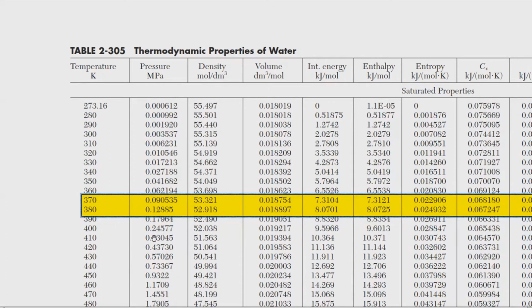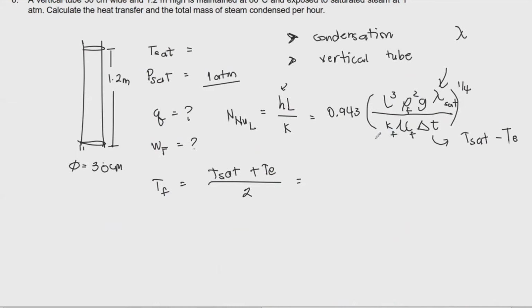That should be expected, but it's not really that exact 100 degrees Celsius. So with that, I still need to interpolate in between. Upon interpolation, by taking 101.325, the saturation temperature is around 99.6661 degrees Celsius. So that's very close to 100 degrees Celsius.